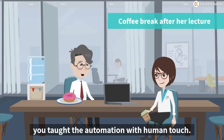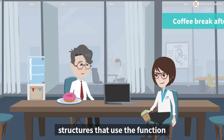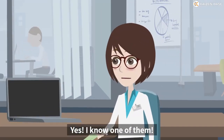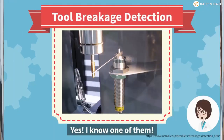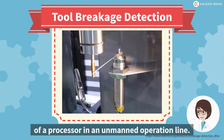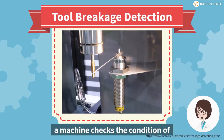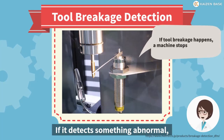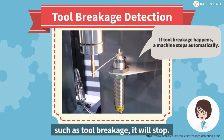Mio, you learned about the automation with human touch. Do you know any examples of structures that use the function to stop in an abnormal state? Yes. I know one of them. The idea is used by the tool breakage abnormality detection of a processor in an unmanned operation line. In the machining process, a machine checks the condition of a tool every cycle automatically. If it detects something abnormal, such as tool breakage, it will stop.